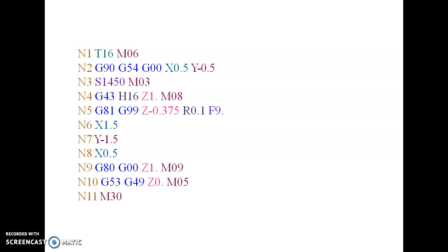First one N1, that is a sequence number, T16 M06, that is a tool change, tool number 16. The M06 is an automatic tool change, and tool number 16.